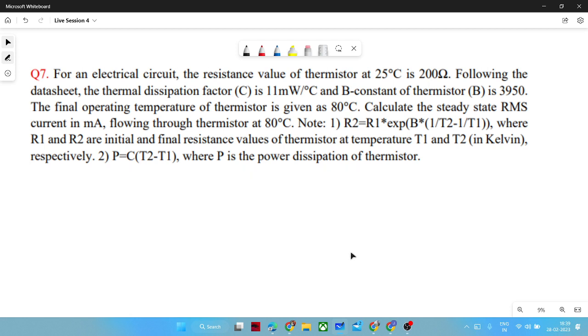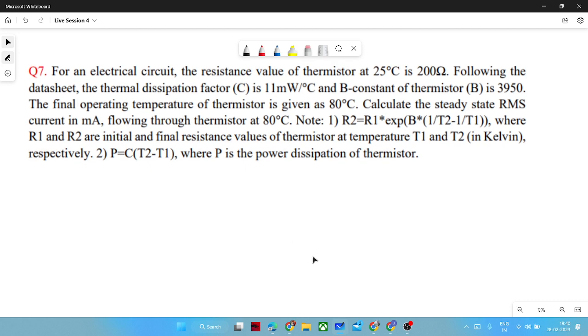If we have a higher value of resistance at steady state, then the majority of the losses will occur in the component itself rather than at the output. So that's the purpose of a thermistor that was not being fulfilled by the resistor, right? So that's why we moved to the thermistor, and that gives us the desirable outcome.